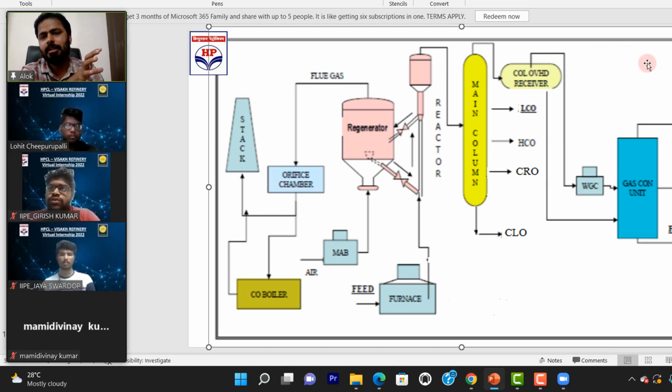So normally the unit won't run like that, based on the process flow diagram alone. There will be interlocks and many safety guards. When you are sitting at the DCS, if you ever get the opportunity to operate it, you will realize how much criticality is there. There are a lot of interlocks; if you deviate any parameter, an automatic shutdown will happen. And you yourself will start taking actions as per the procedure. So the temperature around 505 or 510 degrees Celsius must be maintained.